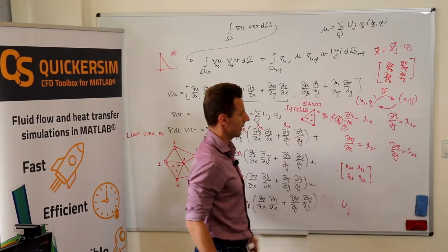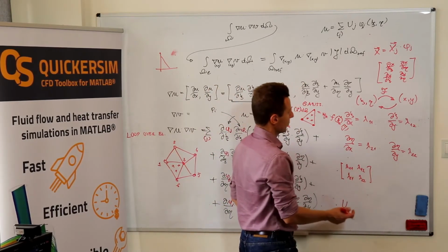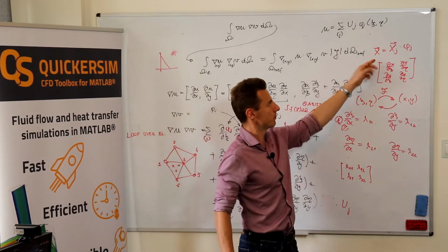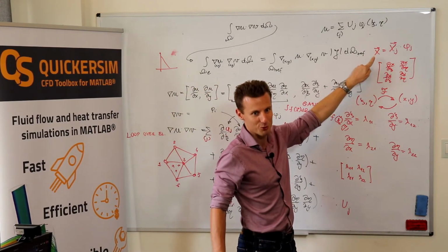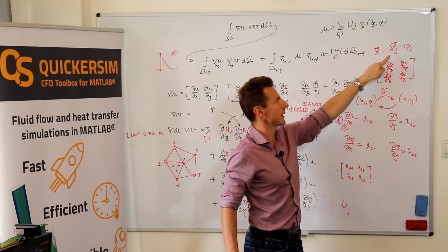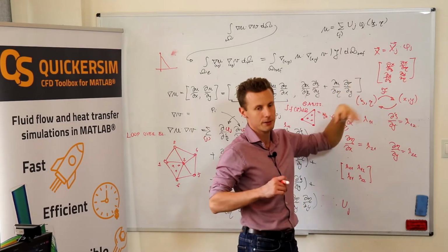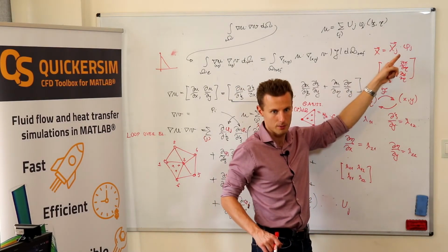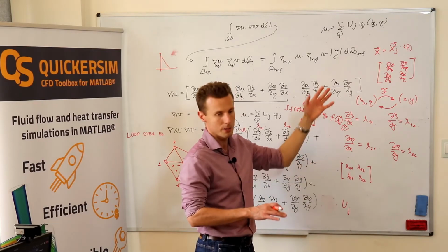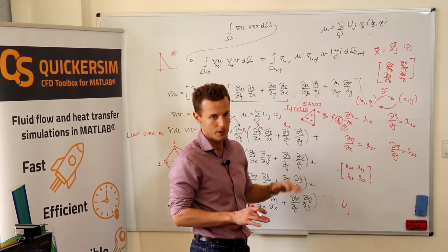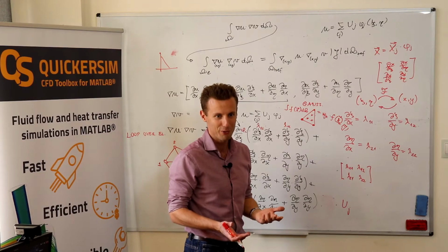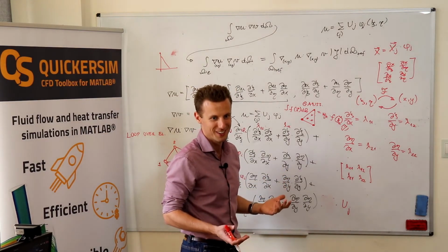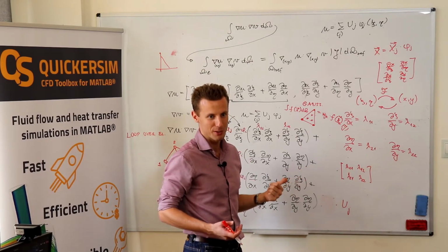Okay. Imagine you want to represent a temperature field. You represent temperature by taking temperature values in the nodes times their associated shape functions, and it spans, for example, the linear interpolation. So what's the difference between temperature and the x coordinate field? If you just take one component, there is no difference.